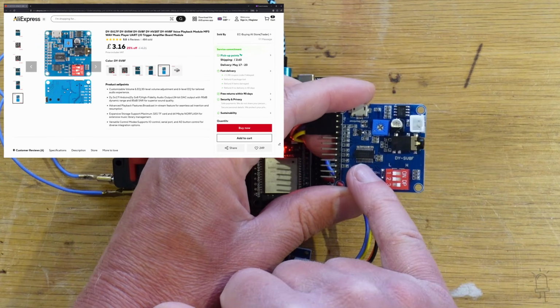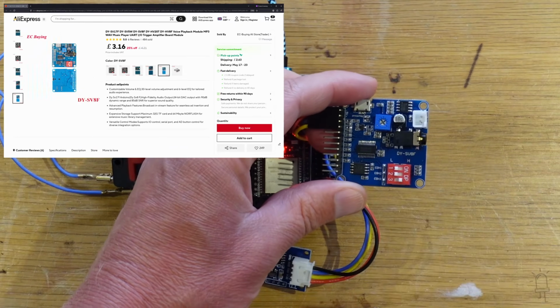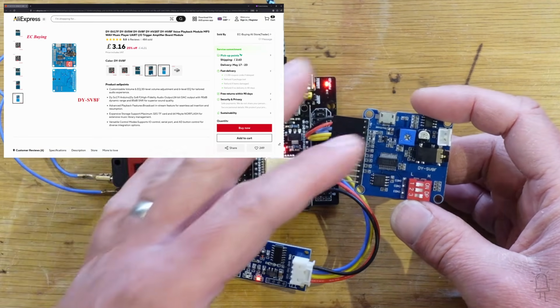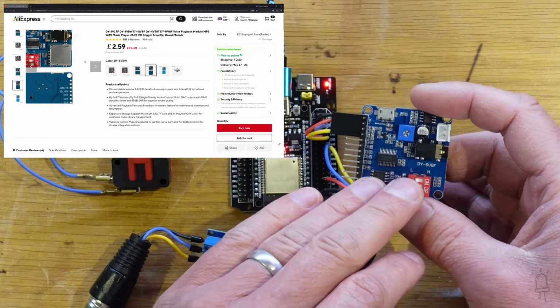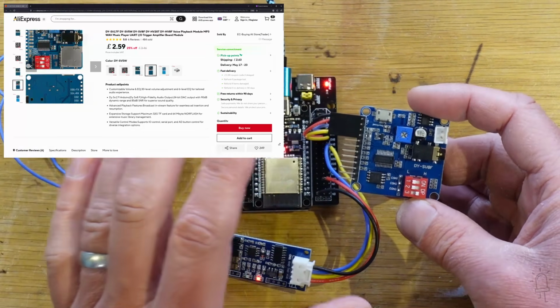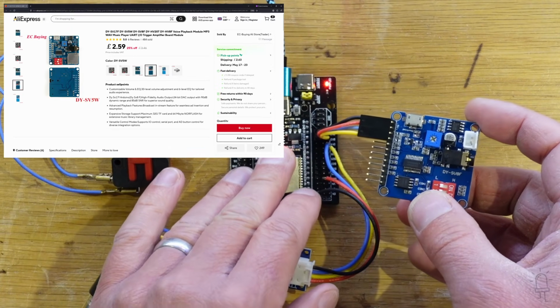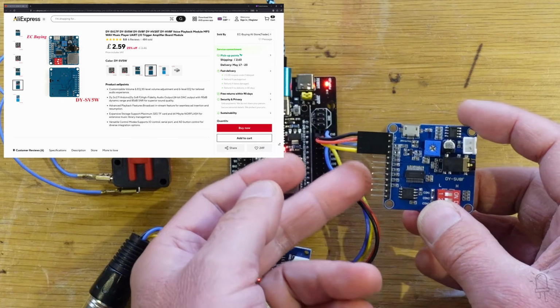Normally you get at most about 8 megabytes of storage on one of these, which is fine if you're mostly playing sound effects or short music clips. But if you want a playlist of full songs, you might prefer to get one of the varieties with an SD card slot instead. Whichever one you choose, you access them the same way, with the same programming interface and the same wiring.